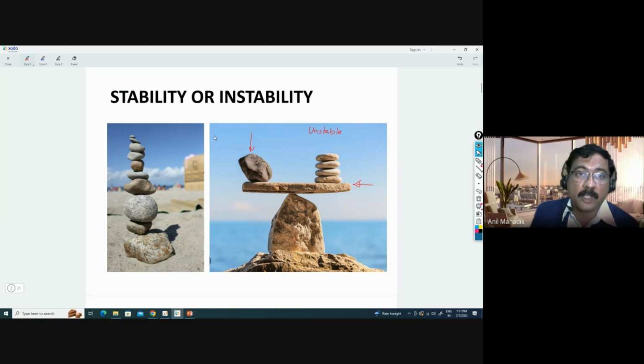If you look at this structure also, it is in equilibrium. Yes, at this moment it is in equilibrium. But whenever I say equilibrium, you know that there are horizontal loads, there are vertical loads, and there are moments. For vertical load, yes, equilibrium is there. If I put a little horizontal load to this, will it be stable? It will fall down. Yes or no? Yes, sir. With load, it will fall down.